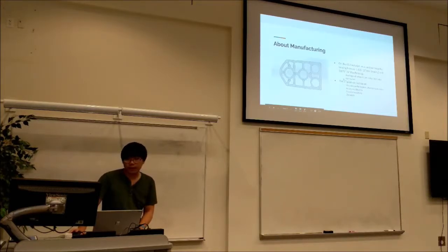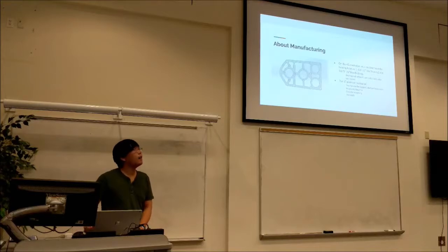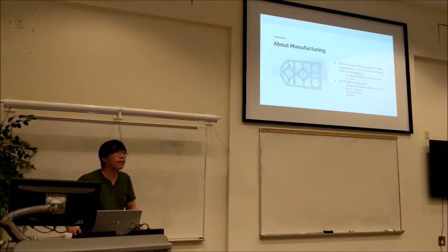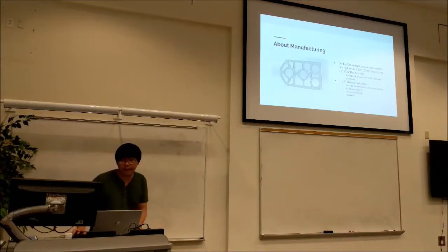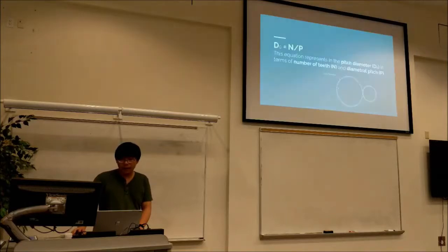And then a few testing notes we did with the KSU water jet. Last year, we dimensioned all of our holes to the exact size of the bearing, so 1.125 and 0.875. Most of the time that did work for us, but we occasionally had to use a reamer to finish off those holes.